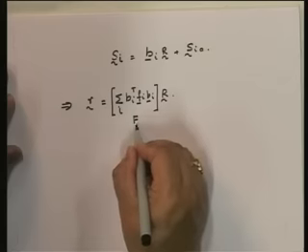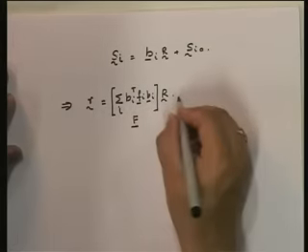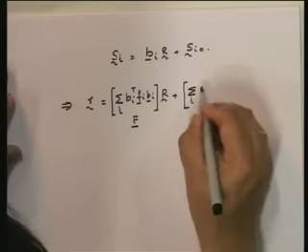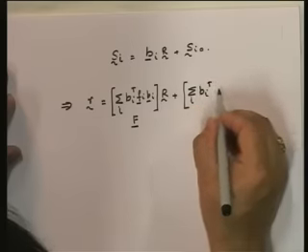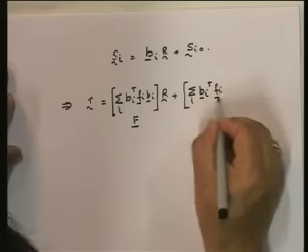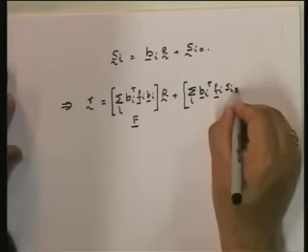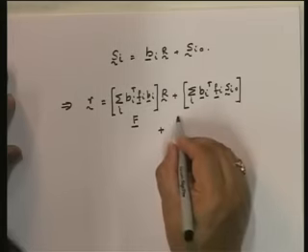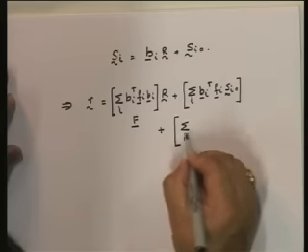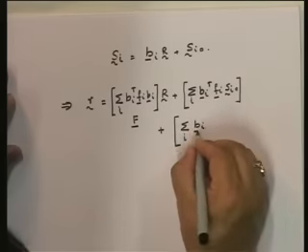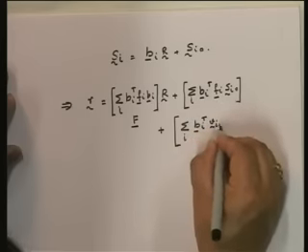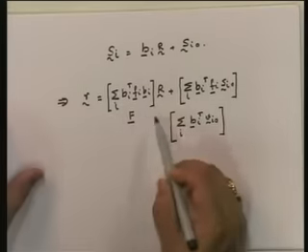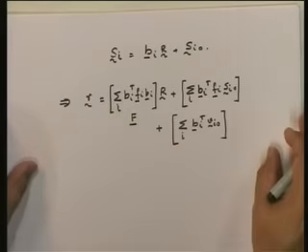This part is the F, the structure flexibility matrix, plus Bi Fi into Si0 plus, summed up over all the members, Bi transpose Vi0. Now understand that this is relating the joint loads to the joint displacements.